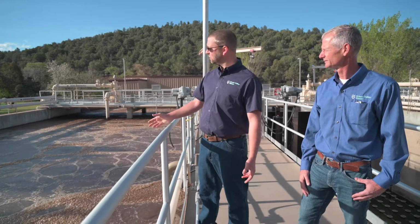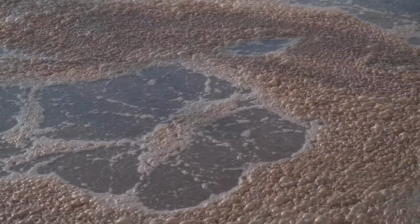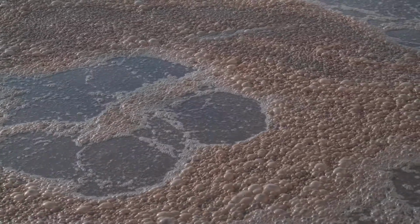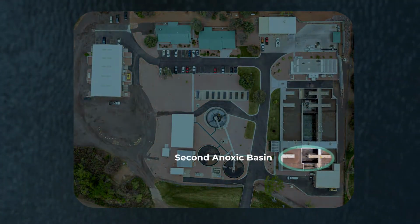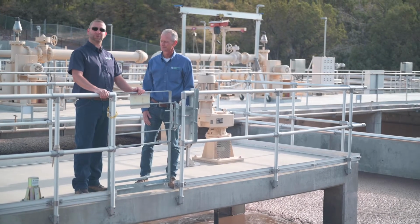In the nitrification process, we add dissolved oxygen, and the bugs use the oxygen and eat all the carbon source that's coming in. The bugs also convert the ammonia into a form of nitrogen that we can remove. So this is the second anoxic zone. This is where we remove the last remaining bit of nitrogen from the process.